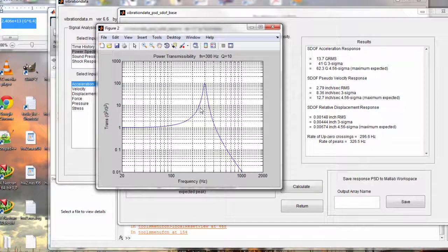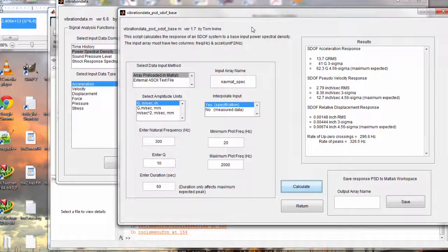And sort of the bottom line, the quick story is, if this were measured data and we were trying to pick off the Q value, we would not say, okay, let's just go over here, pick off Q squared. Instead, it's much better, more robust, to use the half power bandwidth or 3 dB bandwidth method, which we've done before. And I'm not going to repeat that, but we've done that in class before. So for experimental data, please use the half power bandwidth method.